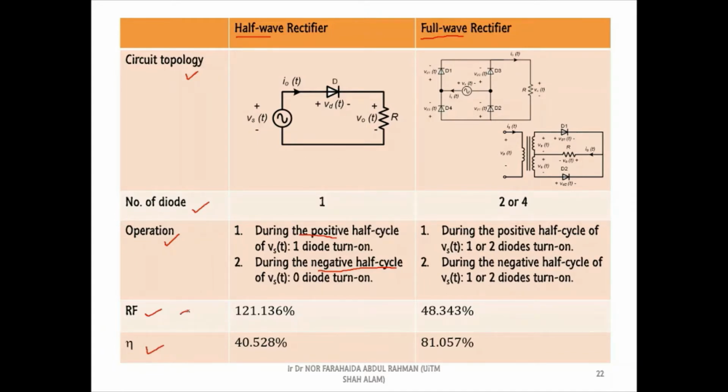Based on these parameters, we can see that the full wave rectifier has lower ripple factor with high efficiency. Because of this, we can claim that the performance of the full wave rectifier is better than the half wave rectifier.